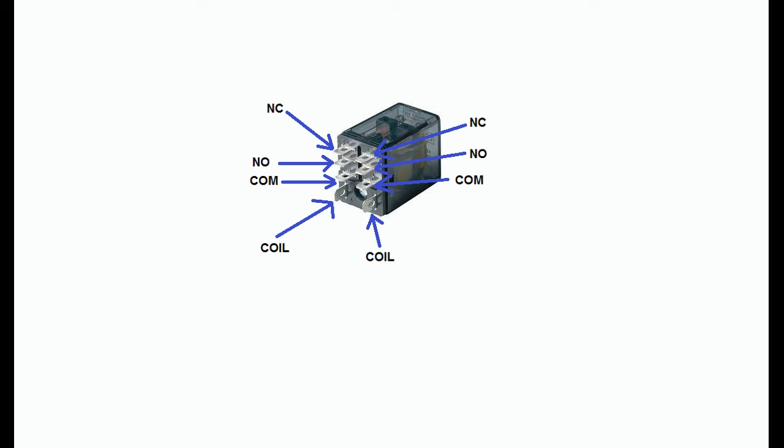A relay, or contactor, is an electromagnetic device composed of a frame, or core, with an electromagnet coil and contacts, some movable and some fixed. The movable contacts, and the conductor that connects them, are mounted via an insulator to a plunger which moves within a bobbin. A coil of copper wire is wound on the bobbin to create an electromagnet. A spring holds the plunger up and away from the electromagnet.